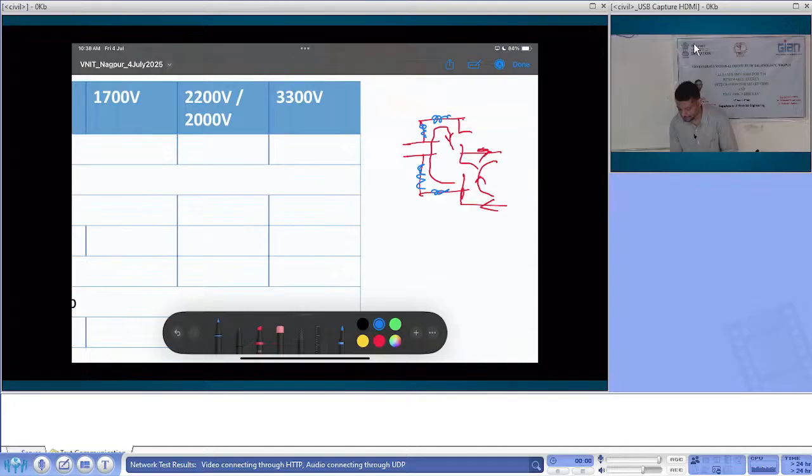And if you have these inductances and a large change in current through that path, it would create a very large voltage spike, right? Because in silicon carbide we can switch very fast, di/dt is even higher, so the voltage spike could be even higher. When we use a module, you cannot really connect things in a more compact fashion. But when you are using discrete, you can do much more. And therefore, if you have not seen, go back and try to Google for GaN devices, right?